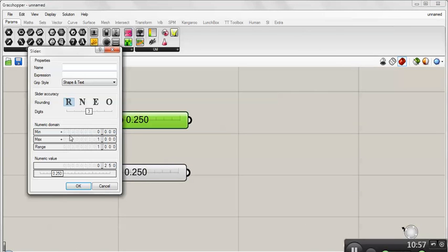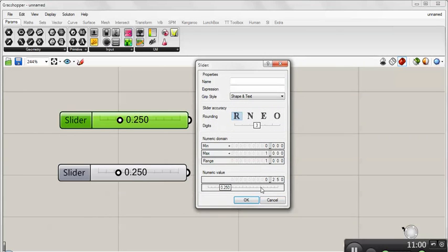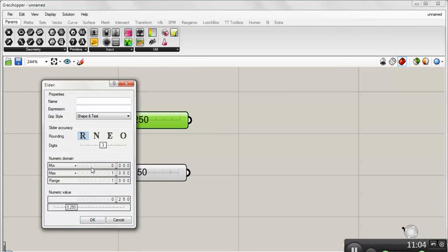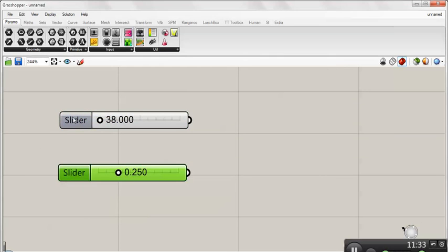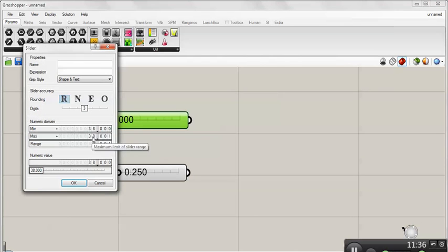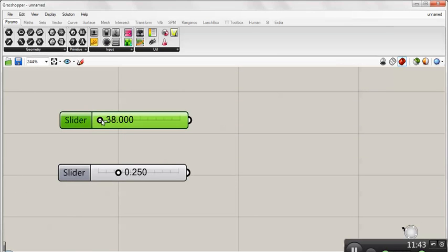Okay, so I'm going to set the range for these, and you double click on the slider, pull that up, or right click, say edit. I'm going to set this range just to the data set so that we don't try to grab stuff that's outside of it. So this will be my latitude, which is the north-south, so I'm going to set it at 38 minimum, 39 maximum, and I'm going to leave it at 3 decimal points to match our selector. I misspoke earlier: 38 minimum, 39 maximum. So that's our data set in terms of north-south.